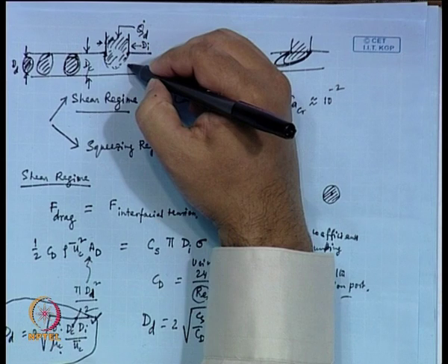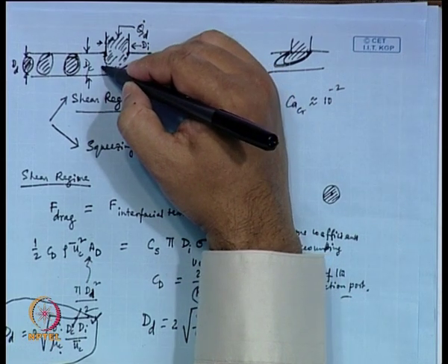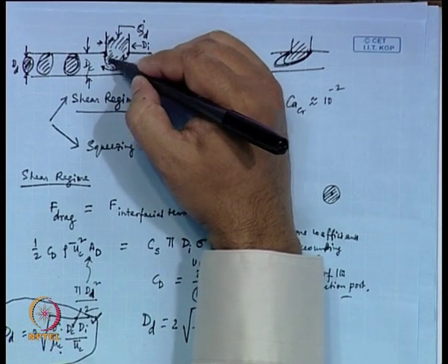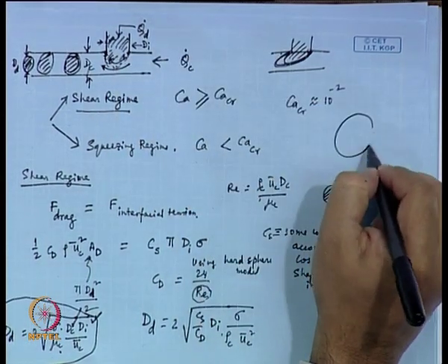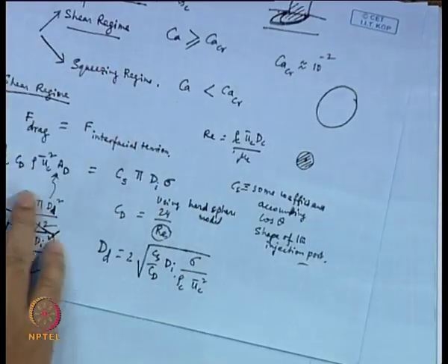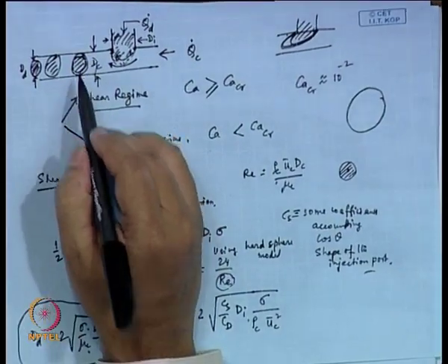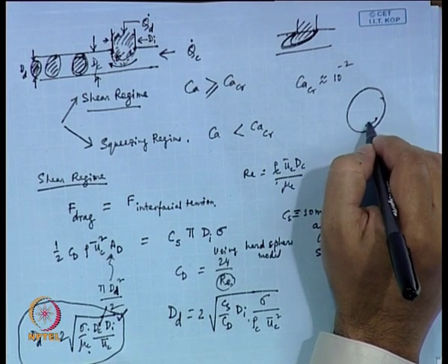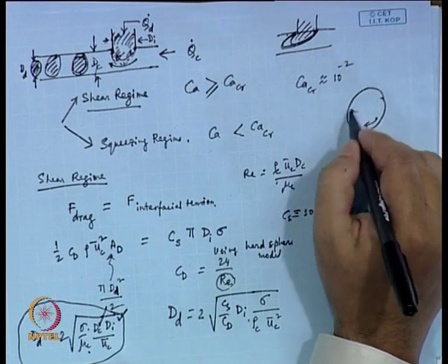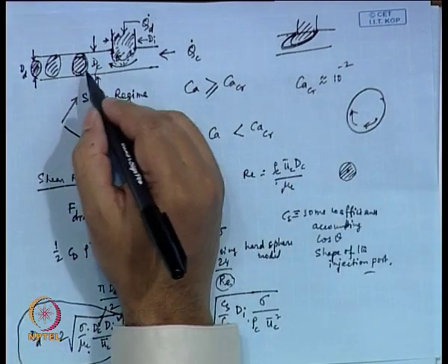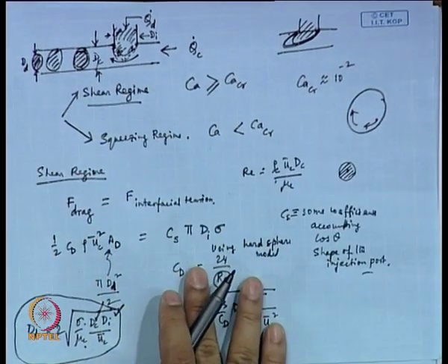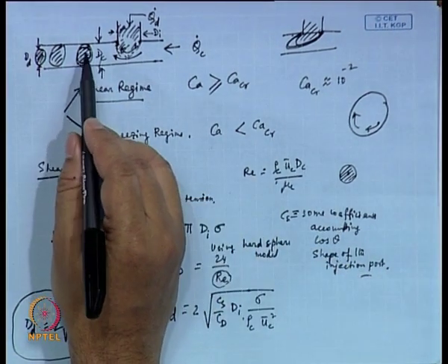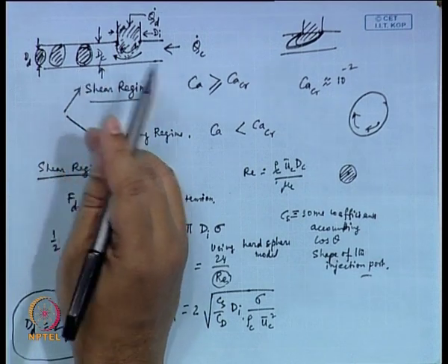Look at it, the carrier fluid is shearing it. So, within the droplet phase itself, there is a shear. If this is the droplet we are talking about, you will find that there is a velocity profile like this. There is a vortex generated within the droplet itself. In fact, this is why there is a proposition that these droplets can be used as a mixer.